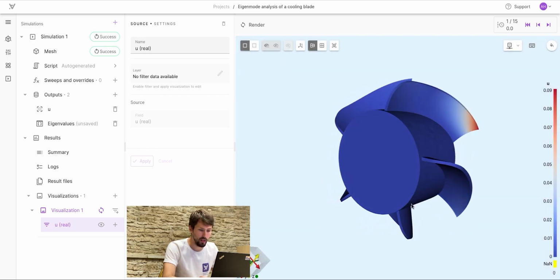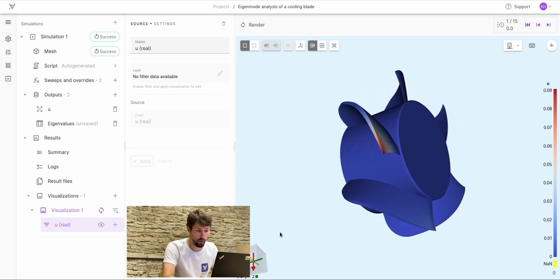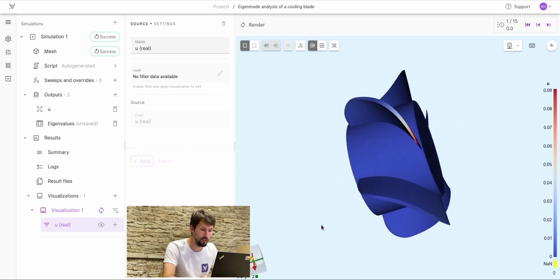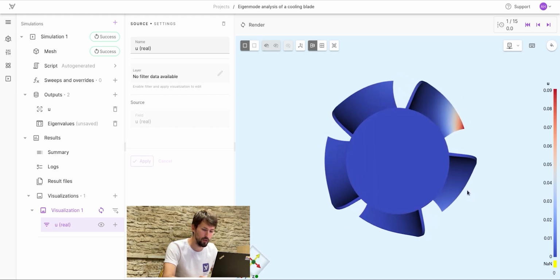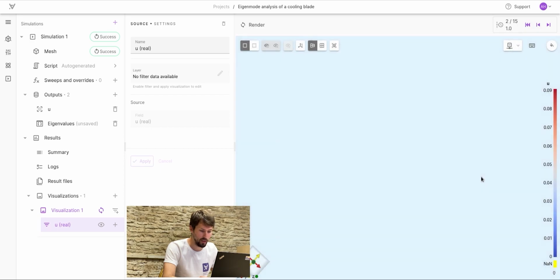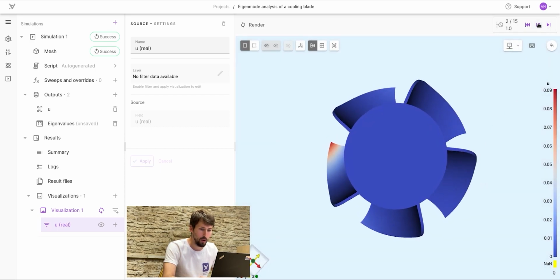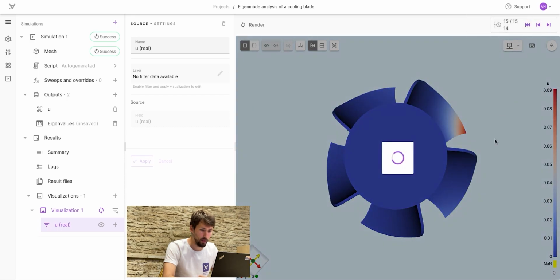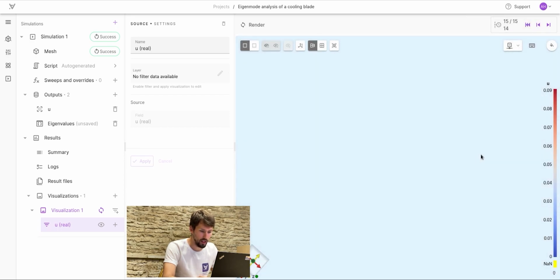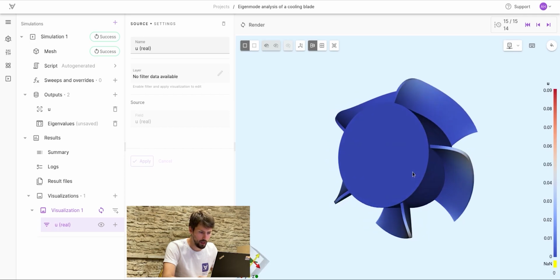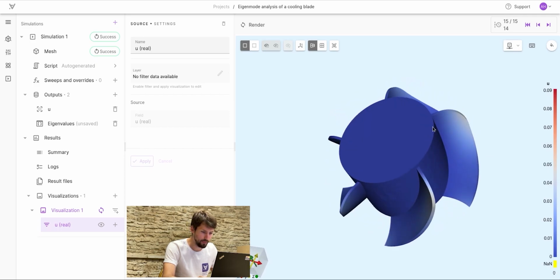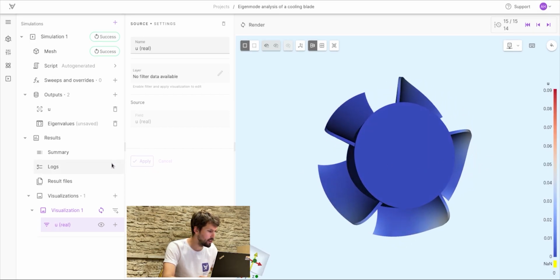So unsurprisingly here for one blade, although all these first 5 modes are clustered really close by in terms of resonance frequency, this is the first vibration mode for the first blade, and then the first 5, unsurprisingly, will each correspond to another blade. And if we want to investigate how the last mode looks, then it will likely be the third vibration mode of the blades. So this is it.